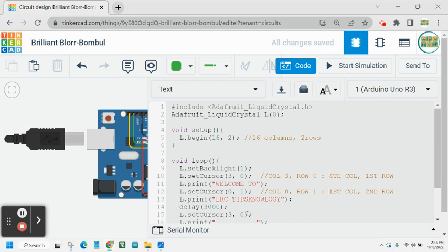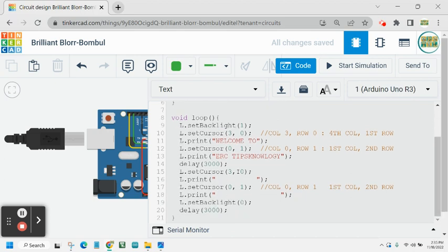And it means that you can position your message anywhere you like as long as it will fit the LCD columns and rows. Now, this part is used so that we can erase the message "Welcome to" selectively. You can do that by using the same column and row that you used for your message before, and displaying blank spaces.